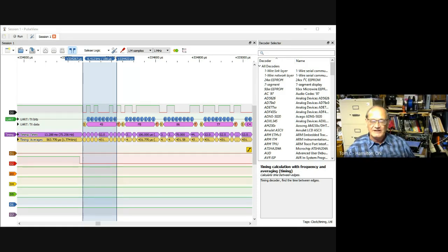But I wouldn't have solved it until I not only looked at the digital logic output, but also looked at what it looked like on the scope. So that's a very worthwhile example. Sometimes the simplest look at what the waveform looks like will help you understand why the digital logic isn't working correctly. Especially as your devices go faster and faster, and you can't look at them with a multimeter and an LED anymore. Yeah. Thought I'd mention that. Had that problem today, and both devices were in use.